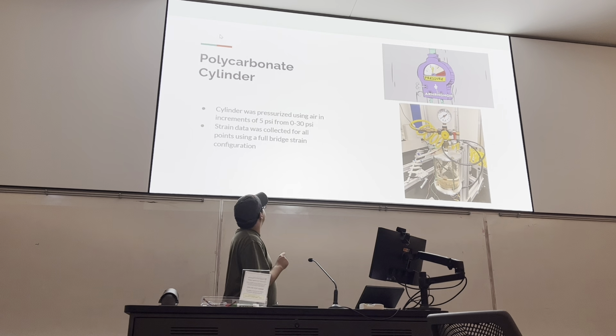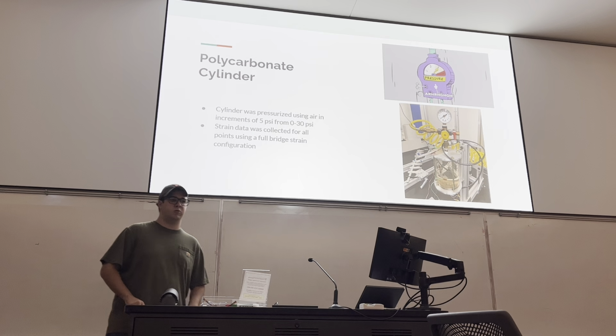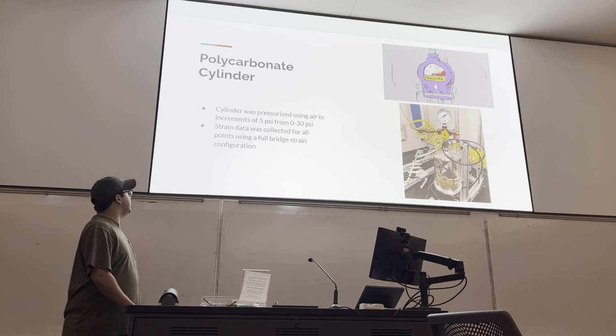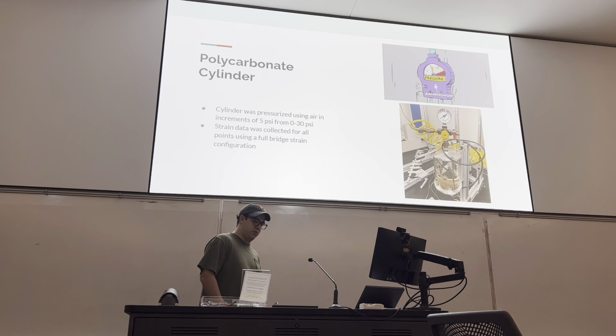Next, what we have is the polycarbonate cylinder, which was pressurized using air in increments of 5 psi from 0 to 30 psi. The information was collected using a full Wheatstone bridge strain configuration.